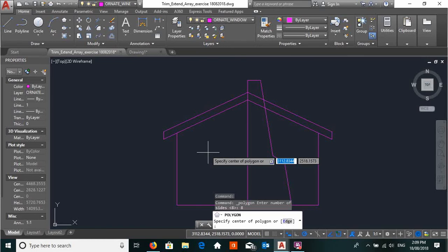I'm just going to tell you what that is, and the measurements for that is that this window needs to be positioned at 1050 in the width, and it has a height of 1650.